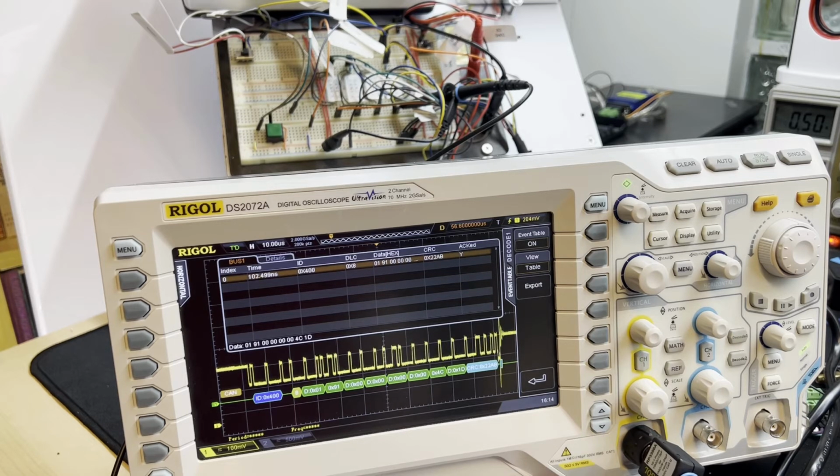The message ID is important as it not only identifies the origin of the message but also the priority. As many nodes may be transmitting on the bus at the same time, they need some way of detecting clashes and prioritizing traffic. The ID does this as when nodes transmit they also listen on the bus for other nodes transmitting their ID, and if they find such traffic, with early bits in the higher priority ID appearing first, then they back off and try again later.